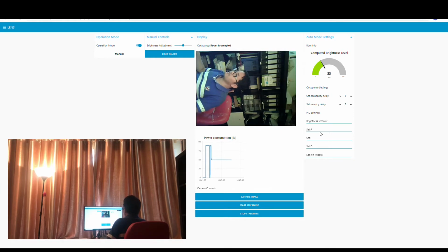Okay, the other feature is the PID control. So we can control the brightness. The system will automate the brightness control operation. In order to do that, let me set the desired brightness point. Let's say we make it somewhere around 30, 35. Because of the maximum brightness, let me increase this to maximum. If we drive maximum power to the light, we achieve somewhere around 39, right?